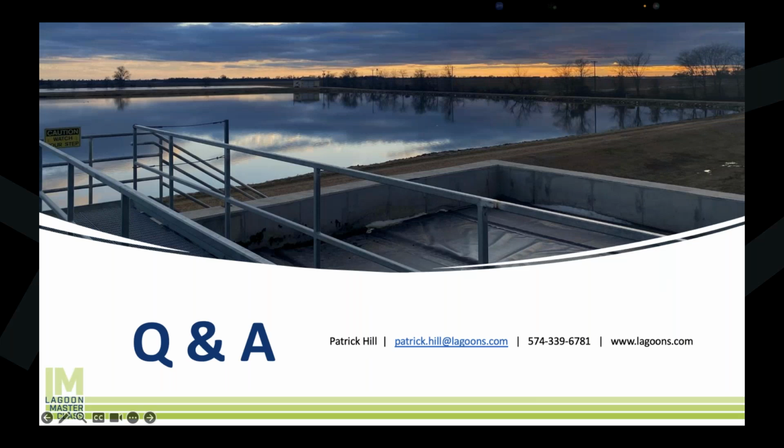body. Because sludge has such an impact on overall lagoon treatment, how often do you recommend doing a full sludge survey? And is this something you can do yourself? At least once a year. And yes, you can absolutely do it yourself. So again, I recommend watching the specific webinar we have that deals with how to do a sludge survey. It's not that hard. For most lagoons, it would take probably a day and a half and 2 people. But at least once a year. Ideally, if you're going to get out there and do a DO profile and things like that, I recommend twice a year, because it's not that hard once you're on a boat and you set up the grid to do that as well. But yeah, once a year.